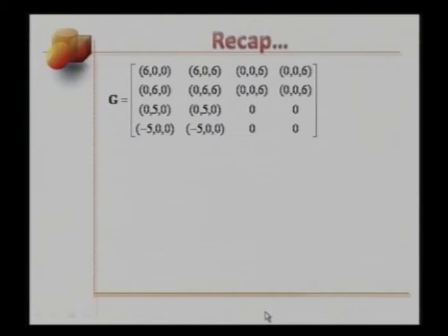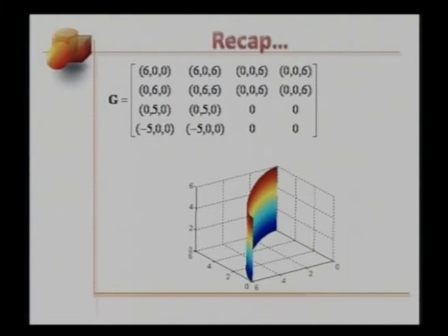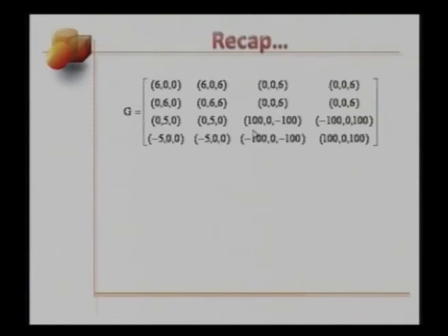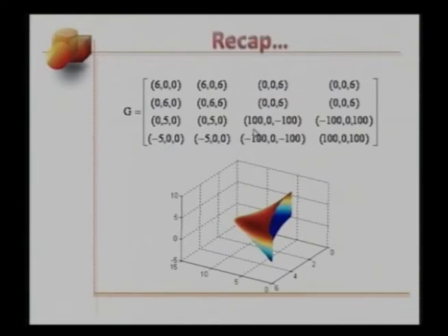we looked at 2 examples last time, one corresponding to this geometric matrix where the twist vectors were specified 0 and the slopes along the v parameter direction and the slopes along the u parameter direction were specified arbitrarily. This is the result that we got for this geometric matrix. And if we specified the twist vectors to be non-zero and arbitrary, for example, through this geometric matrix, we got a significantly different result. The point that I am making here is that it's not intuitive for us to predict shape changes if we specify the slope and the twist vector information in different ways.